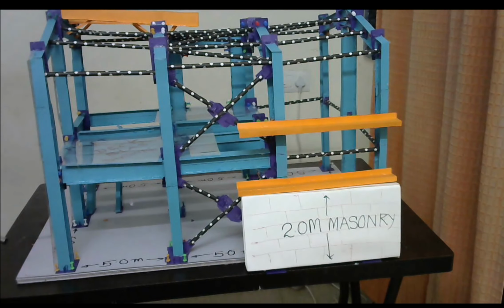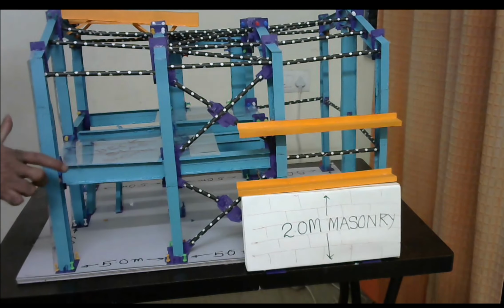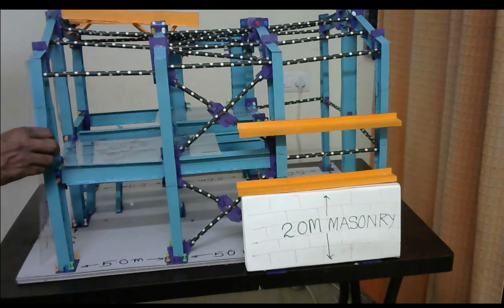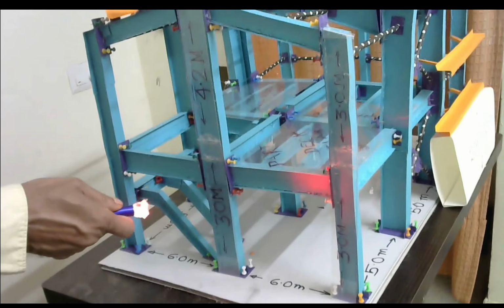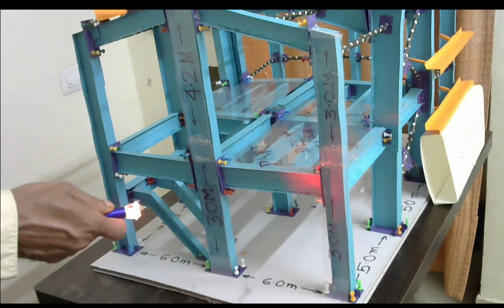Now, what is the LX parameter? For this column, we have defined the LX parameter. The LX parameter is what restrains the column from twisting. It could try to twist like this. Now see, for this column, there is a moment connection here. See, end plate connection.